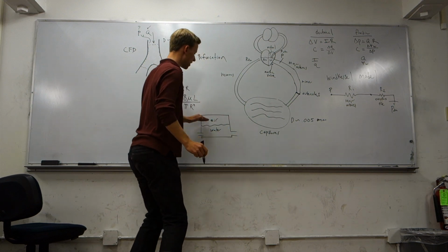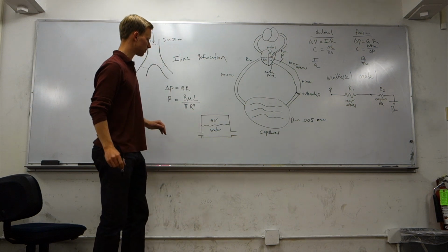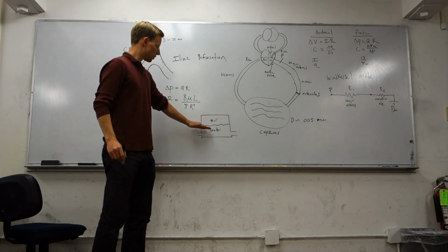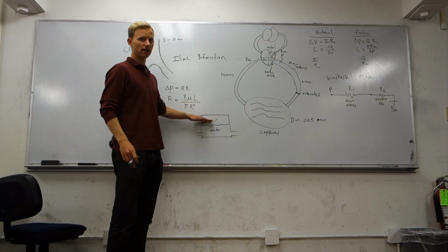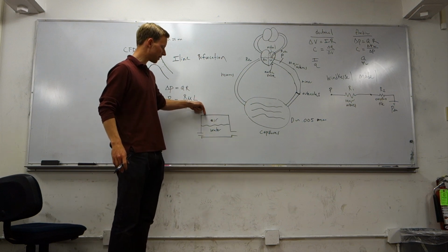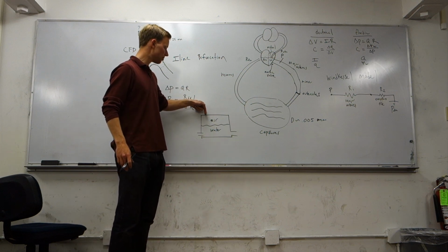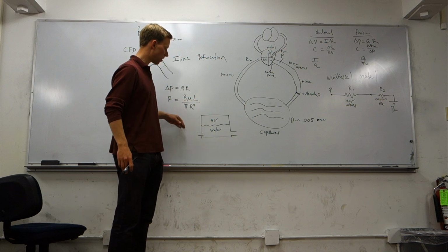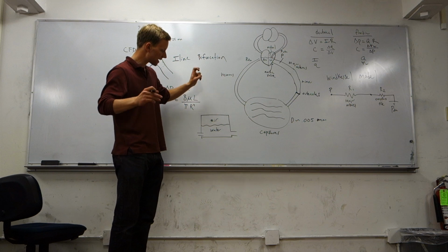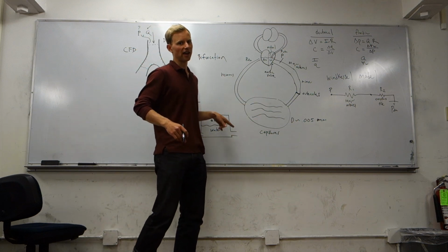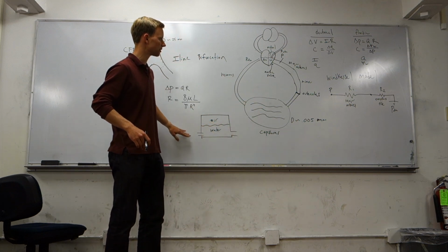The accumulation of volume is analogous to the accumulation of charge on the capacitor. So when you accumulate volume of water, the air gets compressed, so the pressure in the air goes up, so the restoring force back on the free surface of the water goes up. So during a low pressure stroke of your heart, you have higher pressure inside your capacitor to move fluid through and dampen out the high pressure pulses.